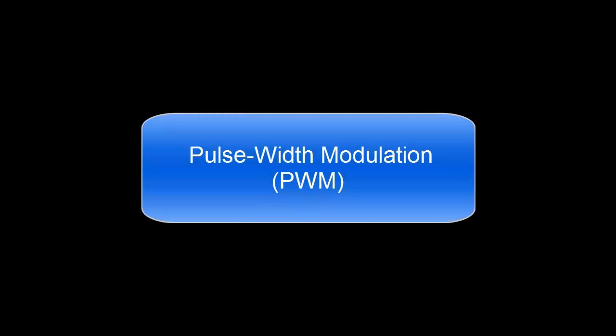And we're going to do this by using a function called pulse width modulation. Pulse width modulation, which is abbreviated as PWM, allows us to use one of the output pins on our PSOC to produce a regular string of high and low pulses. These high and low pulses will occur at a specified interval. Whenever the pulse of voltage on the pin goes high, the light will go on. And whenever the pulse goes low, the light will turn off.